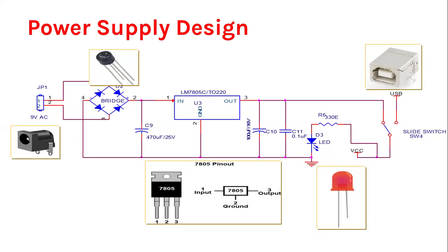And if that pin is used as an input pin, it is capable of taking in 10 milliamperes to 50 milliamperes of current and 5 volts only. Is it clear? If you are using an output component, the capabilities given are 5 milliamperes of current and 5 volts of voltage.